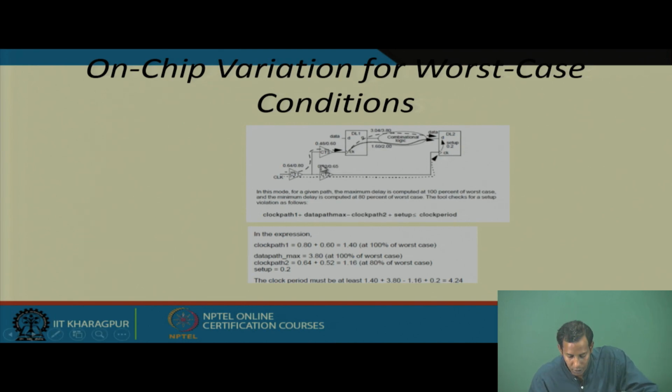That means if this delay information is already given to me, then only I can use it to calculate the time requirement for setup or hold in any of these circuits. Here you can do it manually, as you have only 2 registers and only 1 or 2 paths. That is why it is much easier.